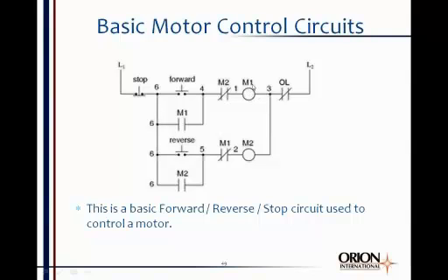If we energize coil M1, immediately this seal-in contact closes. So now I've closed this contact, which allows current flow around the forward push button, and I take my finger off the forward push button, and this seal-in contact allows current flow to maintain current to the M1 coil. Okay? And when M1 energizes, this normally closed M1 contact opens. Well, the purpose of that M1 contact is to prevent you from energizing both the forward coil, the M1 coil, and the reverse coil, the M2 coil.